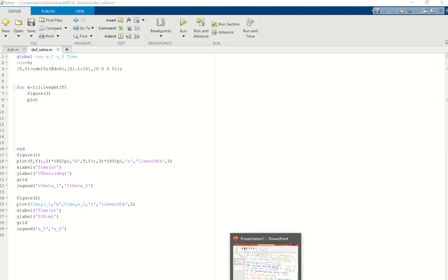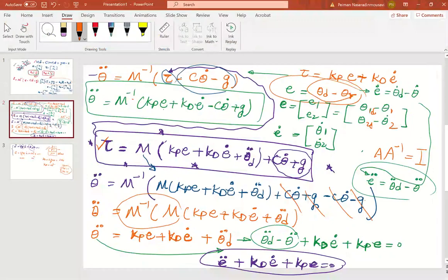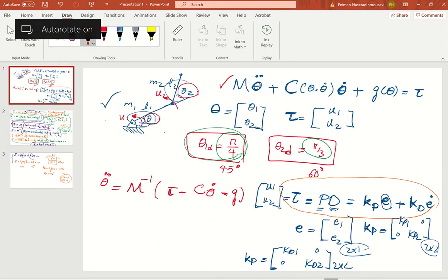Okay guys, let me show it here first because it's too much for you. If you want to plot this in Matlab and make a movie, you have to give x and y of this point, and x and y of that point. This is how you plot a line in Matlab. So x and y of this point is 0 and 0.